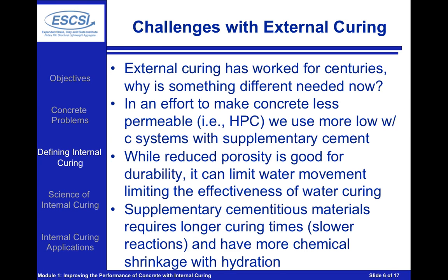Now, as we've talked about external curing, we want to talk a little bit about why there is all of a sudden a need to do something different, or why we can get advantages of doing something a little bit different. So you may be asking yourself, well, external curing has worked for centuries. Why are we doing something new now? And the whole idea here is really, as we move to higher performance concretes, we're able to make less permeable concretes using a lower water to cement ratio and using more supplementary materials.